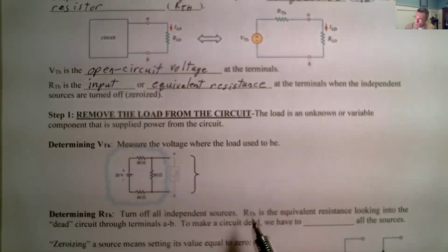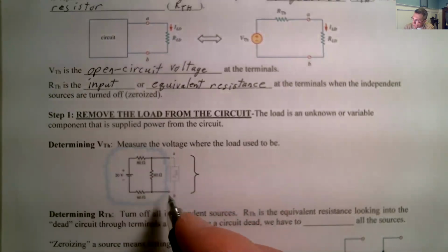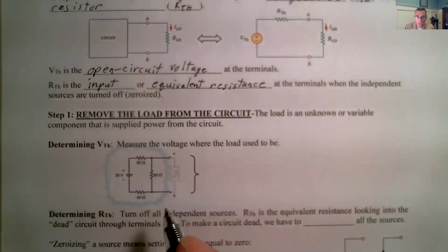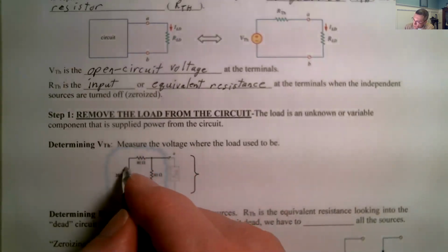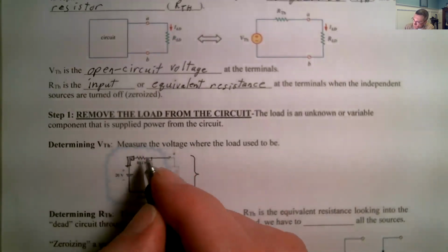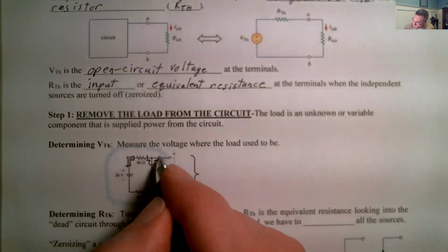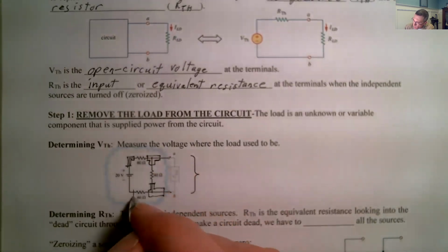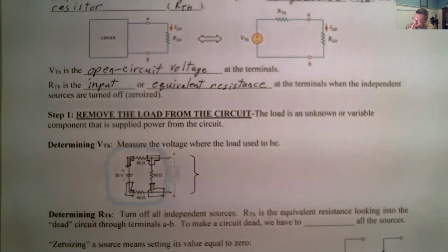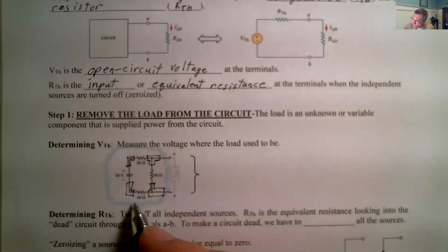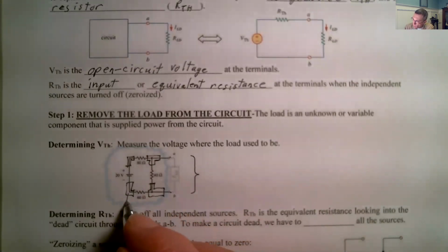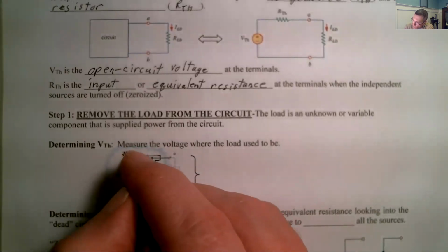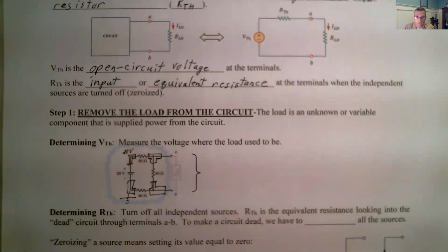we measure the voltage where the load used to be. So we've got this circuit here, and we're trying to figure out what is the voltage between points A and B. Well, the first thing that I usually tell people to do is to identify the nodes. So this is how I identify the nodes. I do a little drawing. I kind of make it boxy because that just works for me. So these are our nodes. We'll designate that one as ground because it's right next to the source. So we know that this one's at 20 volts because we've got the source there, and that's 20 volts.